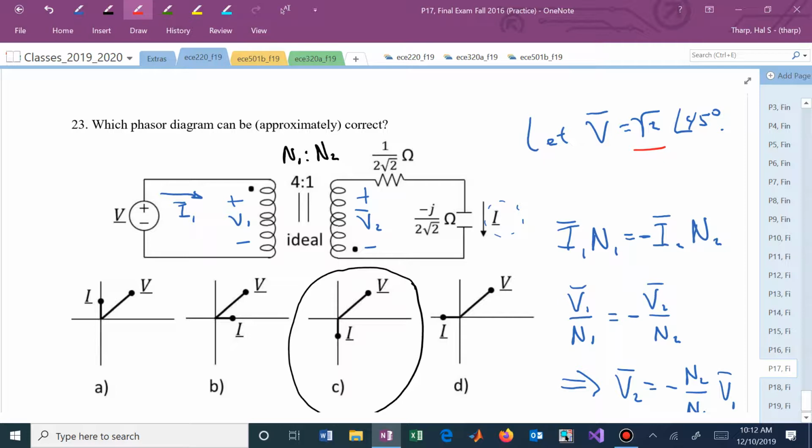If they're in series, if it's capacitors, the capacitive nature is accounted for with the sign of that impedance. You just add them up. So if you had 3 capacitors in series in sinusoidal steady state, you just add up their impedances. You don't go back to Chapter 5 and say, wait a minute, these capacitors are in series. No, compartmentalize and say, wait a minute, what are they asking?